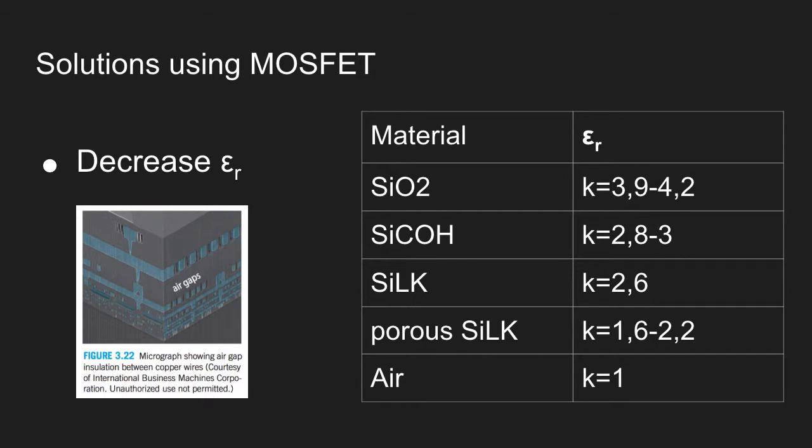Finally, the switching delay of transistors is typically considered to be caused by the capacitance of the transistor gates. However, when transistors become very small, the capacitances between interconnections become greater. As wires get nearer, this capacitance also affects the delay of the transistor.